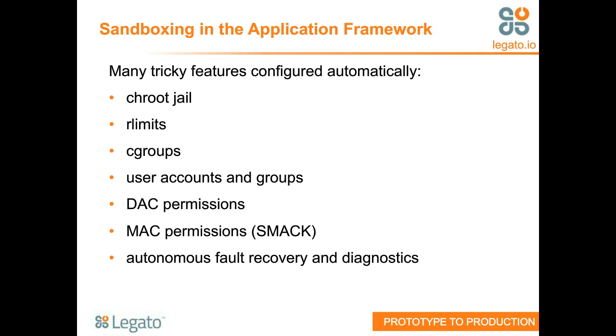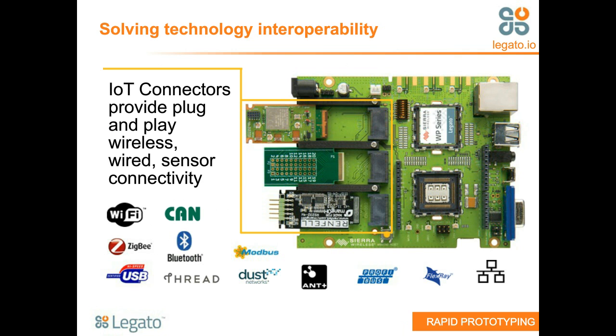Now, bringing it back around to Mango, as Ashish said earlier, when your board powers up, the software detects that there's an IoT connector card in the slot and queries its EEPROM to identify it. It then uses an app control API to start the app that knows how to drive that card. The app can then read sensor data and push it to the cloud, receive commands from the cloud and drive actuators, perform local analysis of sensor data, and react to events by making network connections, sending SMS messages, driving outputs, or whatever your application needs.